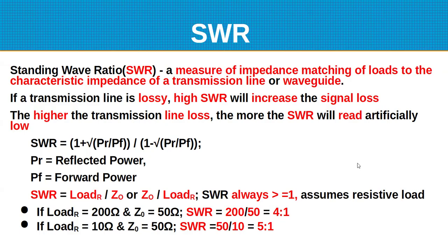So what do you use instead of an SWR meter? Well, I have an SWR power meter, and you can't believe it, it's always going to read low. How low it reads is a function of the loss. So if you have a fairly good match to the antenna and low loss cable, it isn't a big issue. It's basically here because somebody decided it would make a good question.